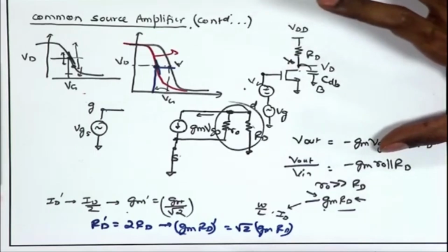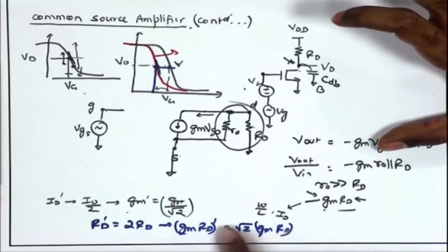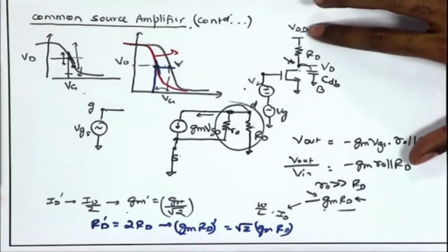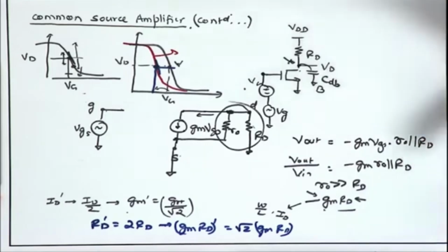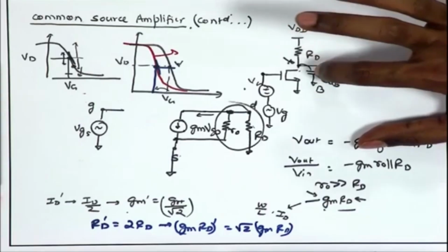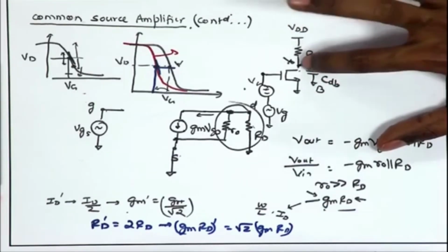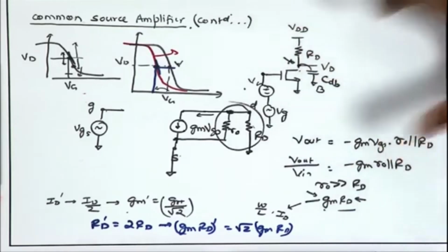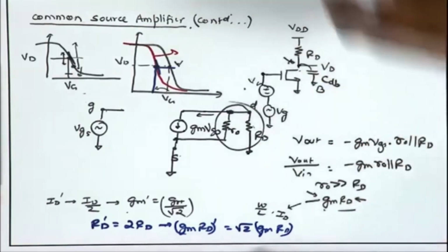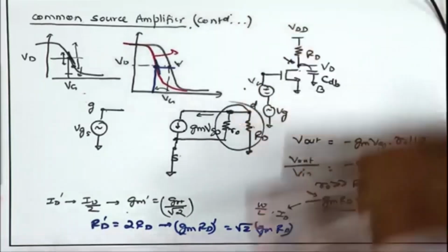Likewise, we have also seen that the Gm can play an important role in determining the noise. So, if the Gm of the input device is going down, although you are trying to maintain a similar gain, once again the input referred noise can be deteriorated. So, once again we have a stringent trade off with other parameters. You are trying to adjust one of the parameters, trying to increase the gain while keeping the swing the same, but other parameters like the bandwidth and the noise are going to degrade, linearity is going to degrade. So, we have to take care of the requirements in the design. While optimizing one parameter, we have to make sure that we are still meeting the other requirements.